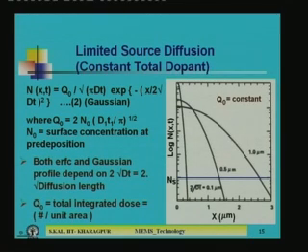You see, initially the surface concentration is here and the supply of dopant atoms is fixed. So if you go for longer diffusion, either by increasing the temperature or the time, the dopant atoms will go much deeper into the silicon, and the surface concentration goes down. If you go for further diffusion, with root Dt of 0.1 micron to 0.5 to 1 micrometer, that means if you increase Dt much more, the surface concentration goes down further, but the junction depth becomes larger and larger.